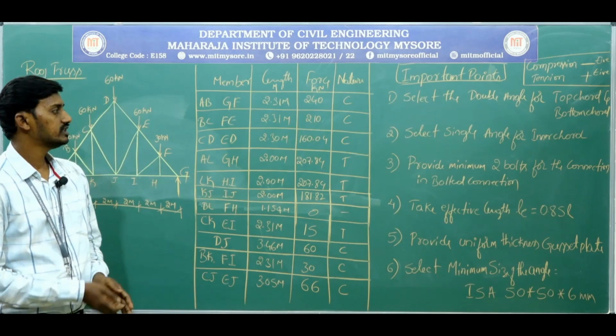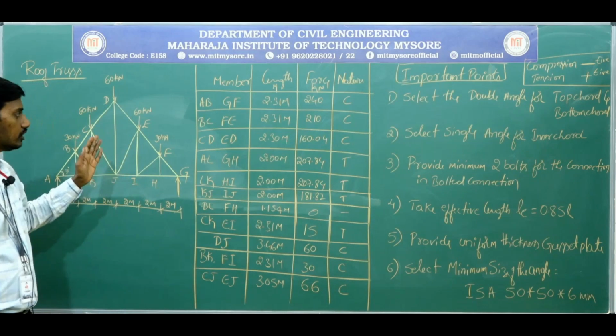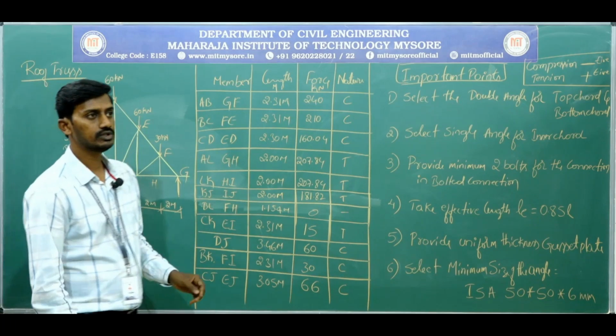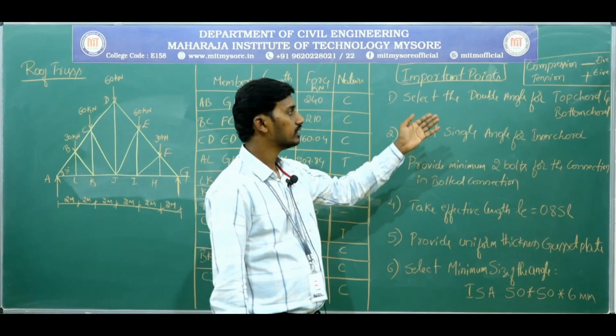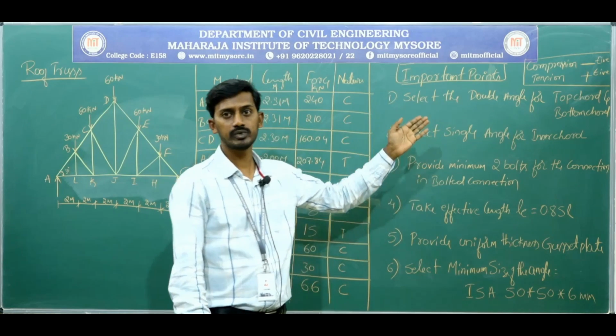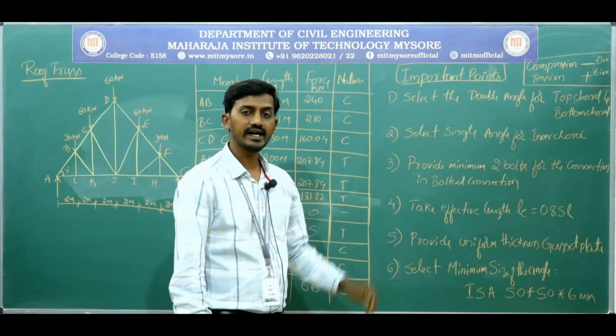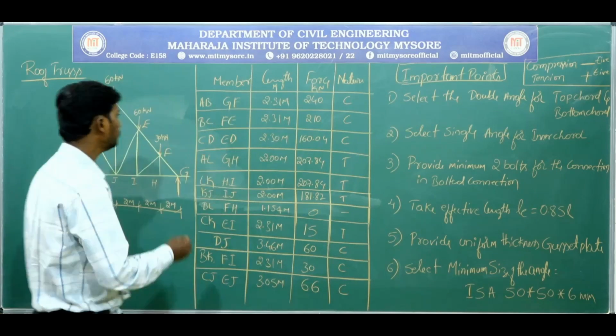With this information, before solving any truss design, we should follow certain steps. You need to remember these points. First, select double angle for top chord and bottom chord.